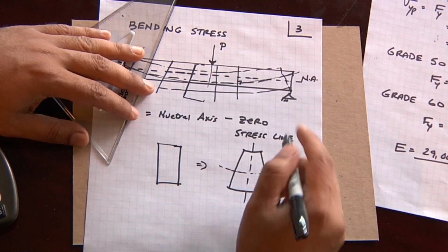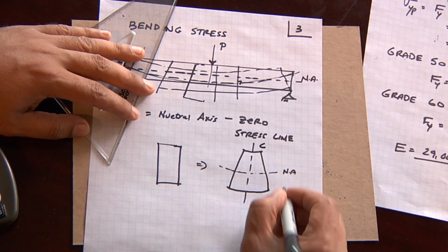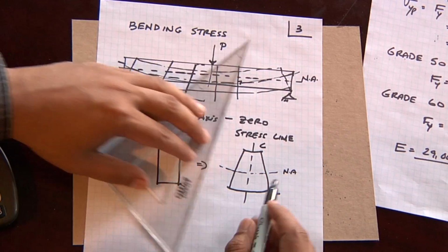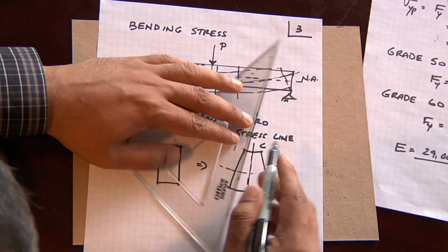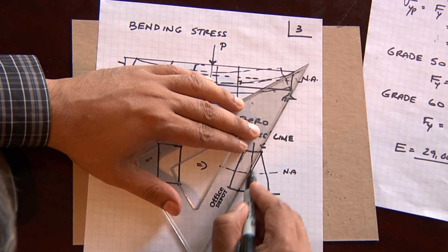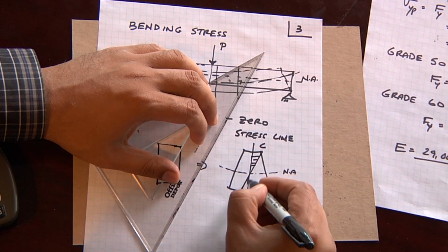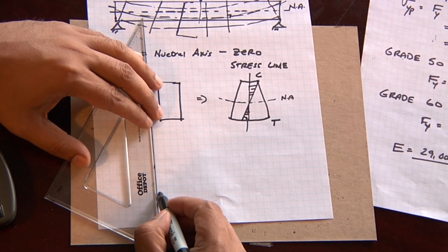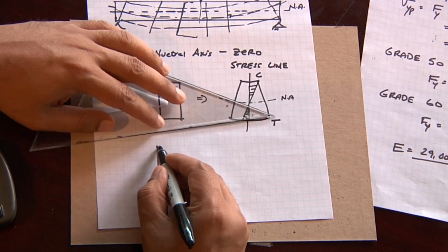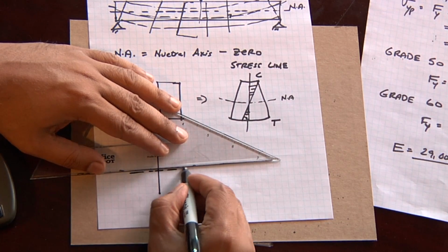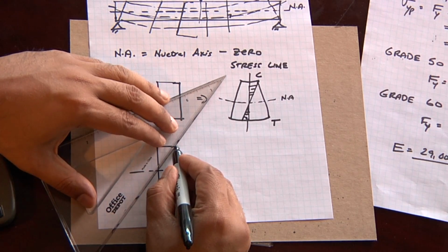The way that it's bending is I'm having compression on the top and tension on the bottom. And so if I graph it, my stress profile is a triangle. I'm not going to go through the math to derive the equation. I just want you to understand where this comes from. So here's my neutral axis. Here's my stress profile.